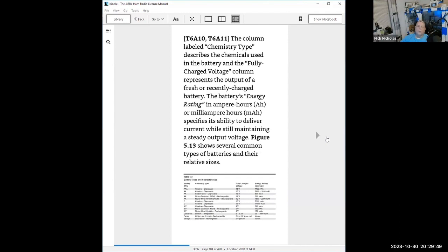So if you want to know how long your system will run on a given battery, you're going to be shocked at how short it is for many transmitters. But that's how you calculate it. Whatever its amp hour rating is, that's how long it lasts per hour at however many amps you're running it on. You divide the amps into its amp hour rating, and you get how long you can run it. I think I said that right.